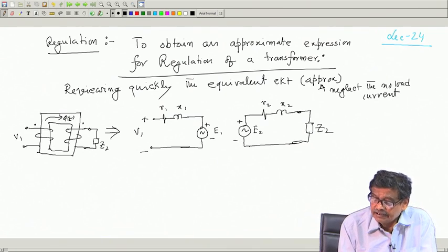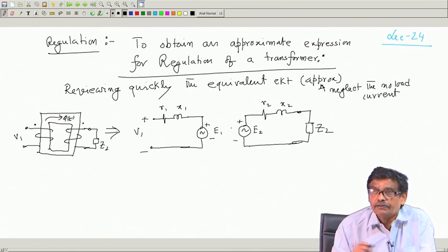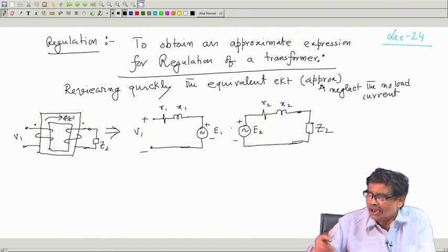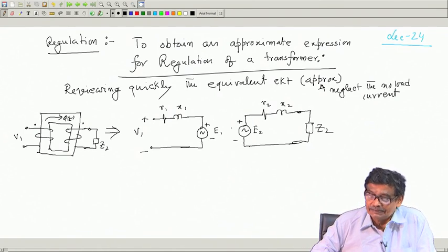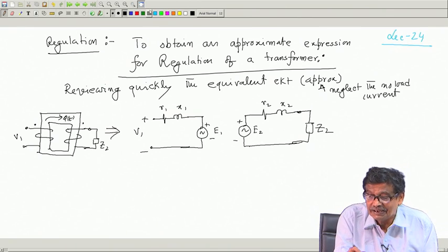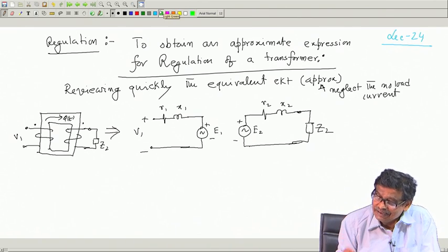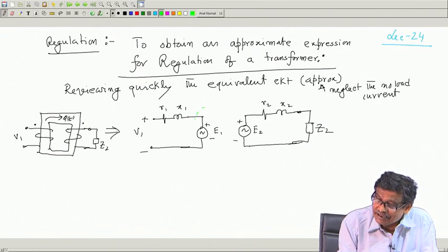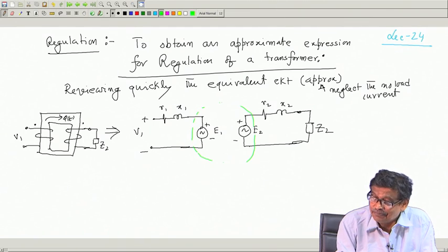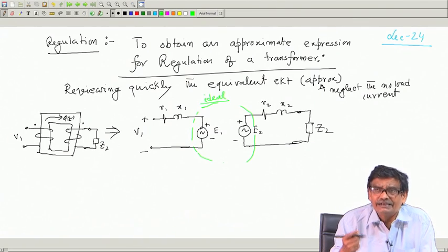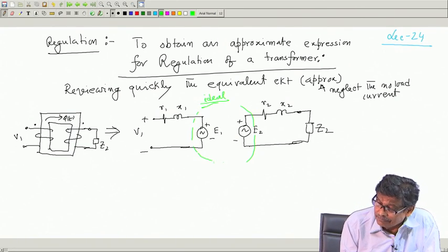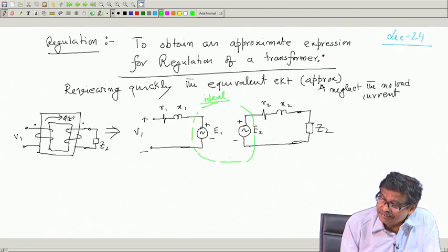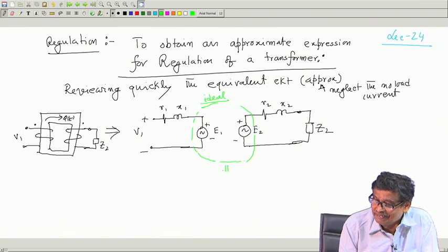This is the ideal transformer primary, this is the ideal transformer secondary. No load current and magnetizing current I have neglected. So, this is like this. Now, the interesting thing is this one, because this portion is ideal, you can view it in different ways. I will tell you to adopt only one of them. What I am trying to tell is, this is the same as this thing.